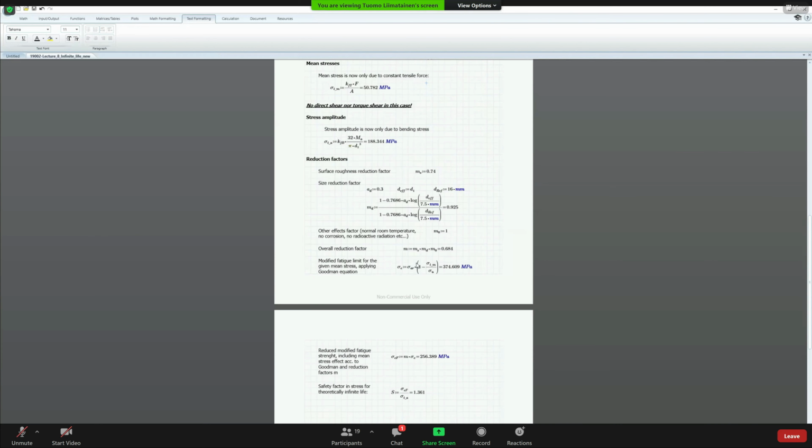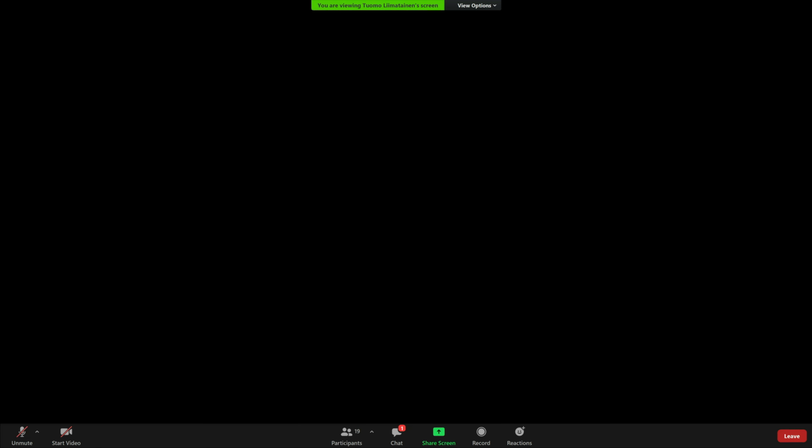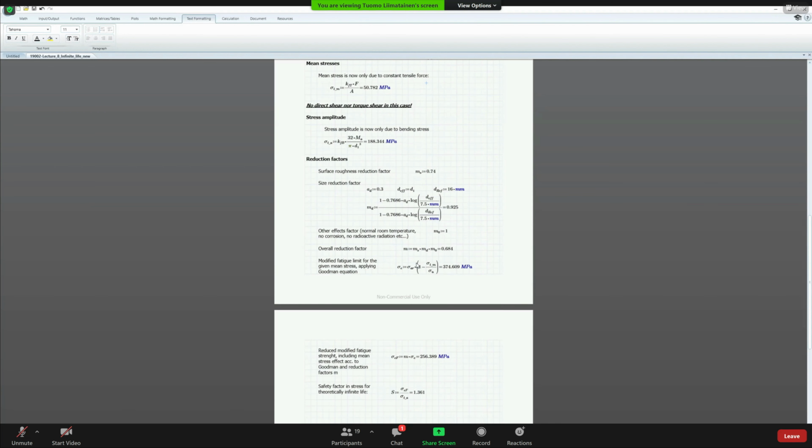Yes? So is the difference between this task and our project work the amount of loads in the first place, and secondly, instead of just simple normal stress, we use mean stress there. Yes, you have to use von Mises for both the amplitude and the mean stress in your project work.